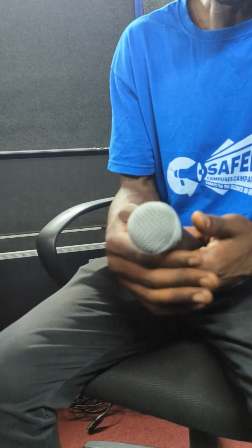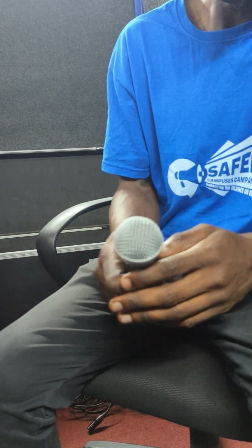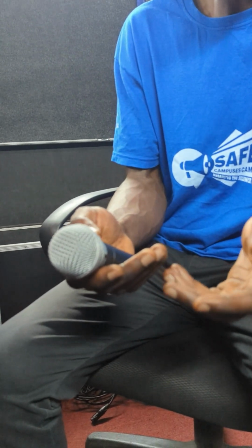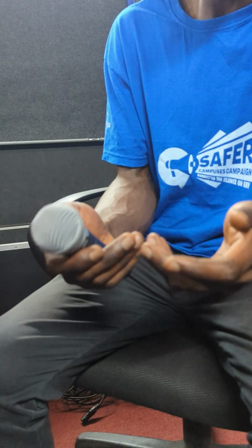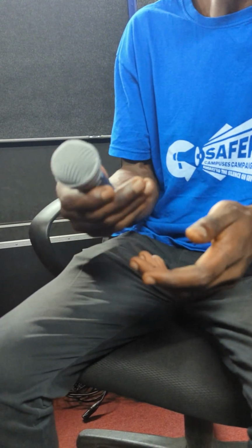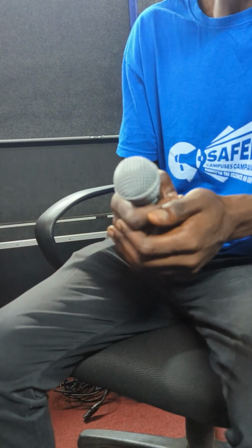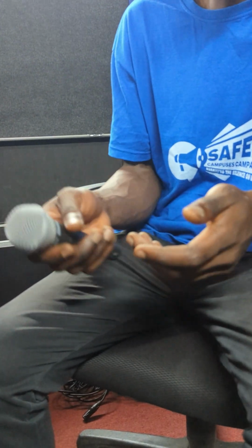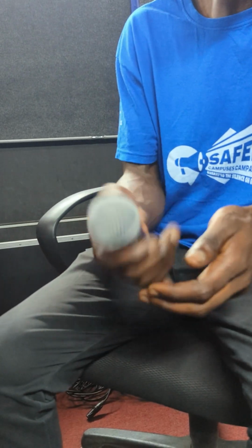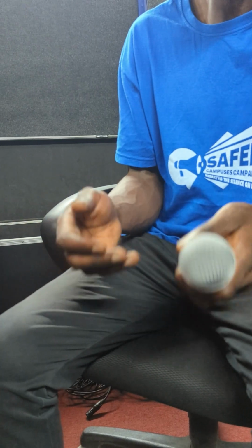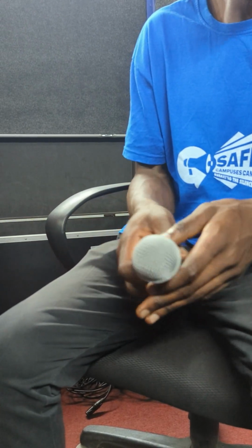And as I've said, the pickup pattern of a dynamic microphone is a cardioid, and these microphones don't have the proximity effect, which is the effect of boosting low-end frequencies, when compared to other microphones, of course, like the condenser microphone, which I'm moving to. So this microphone is good for instruments and voices. They pick sound as it is without boosting the low frequencies. Okay, moving on to the condenser microphone.